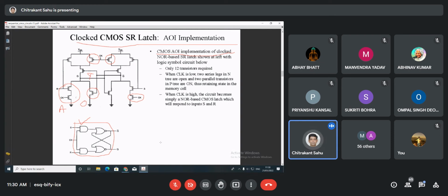If you are preparing it by your own conventional method, then how many transistors may it take? Six alone, and then four. So it will increase the number of transistors. Okay, so it is better to make it in an optimized way by AND-OR-invert logic, so that the number of transistors can be reduced while giving the same functionality for the implementation.